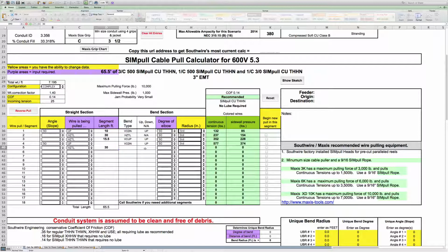And in this case, instead of a 90-degree bend, I'm going to have an offset. Say the offset has two 15-degree bends in it. I can do each one separately, but I'll just combine them in this case and make it a 30-degree bend. Standard radius offsets right there.